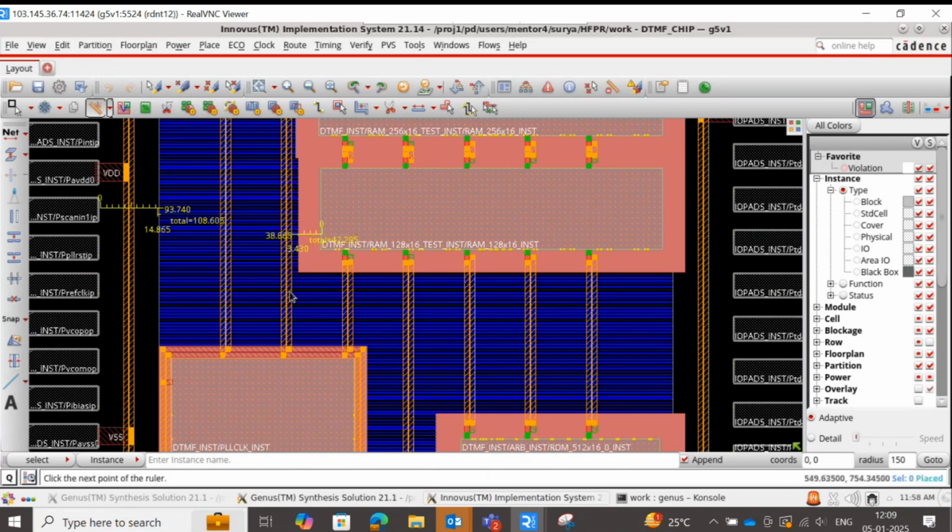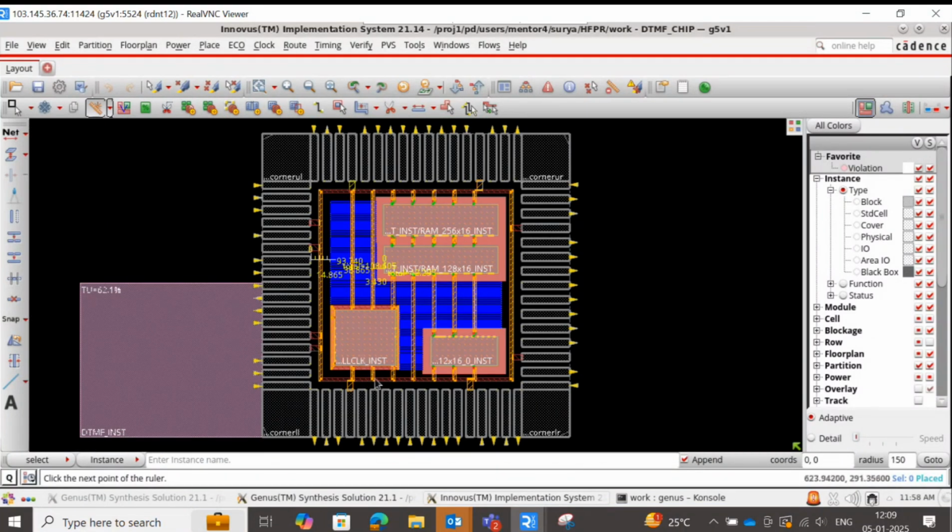And these are your different metal layers. Different metal layers are used, and these are your rings, where you can exactly draw the ring. The advantage of the power ring is that you can directly connect the stripes to the power ring. That's the advantage. All right. Now let's say for example you have the IO pads, right?